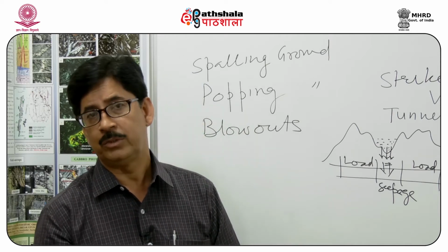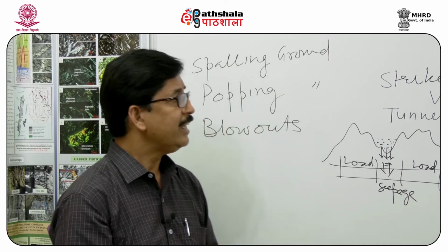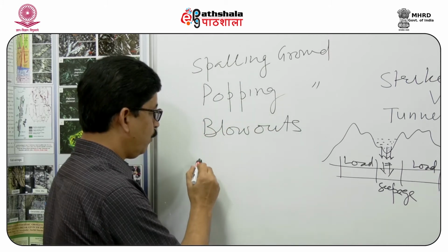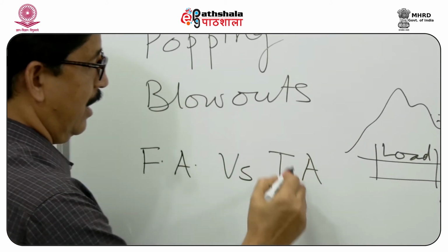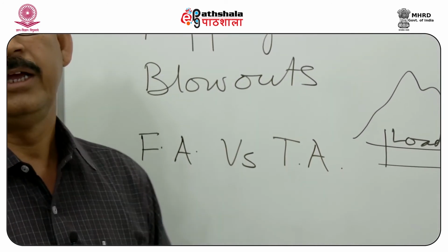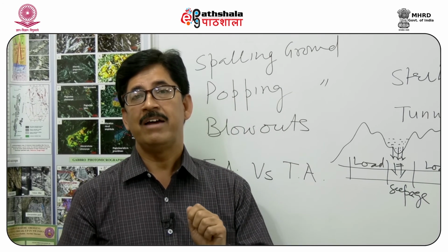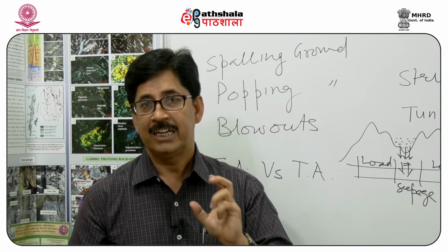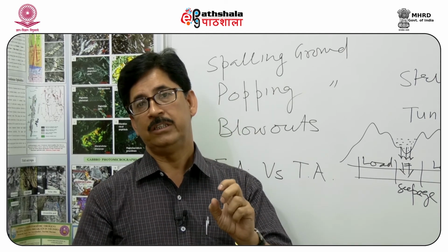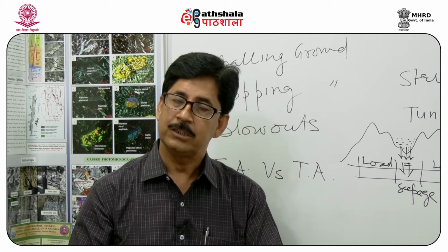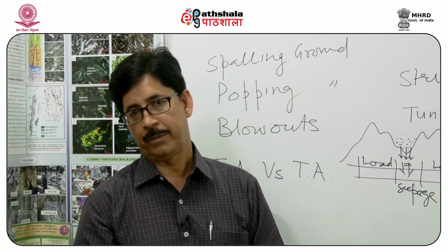Sometimes we may come across a folded sequence of rocks. Now again we have to see what is the relationship of fold axis with tunnel alignment. If we are parallel to the fold axis, then we may have our tunnel along the anticlinal zone or along the synclinal zone or in between the two, as per the situation, as per the alignment, as per the location.